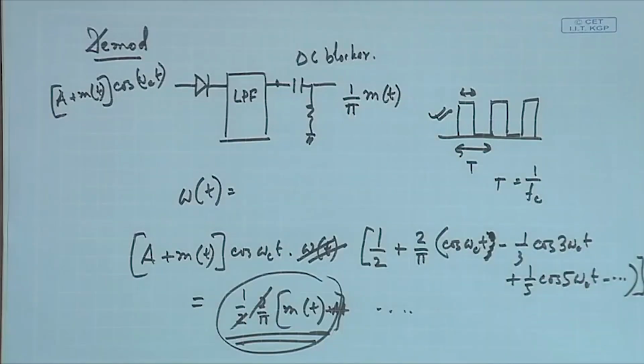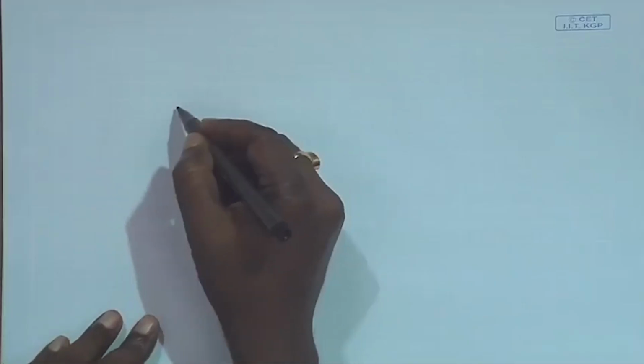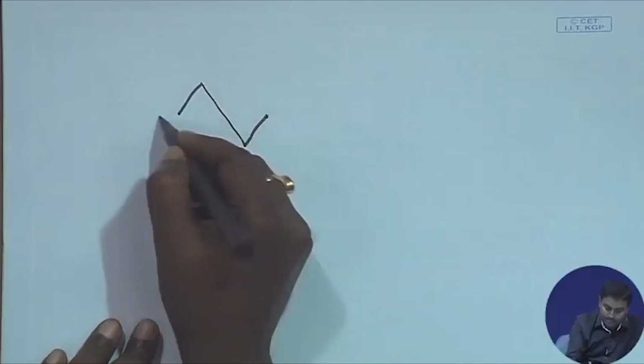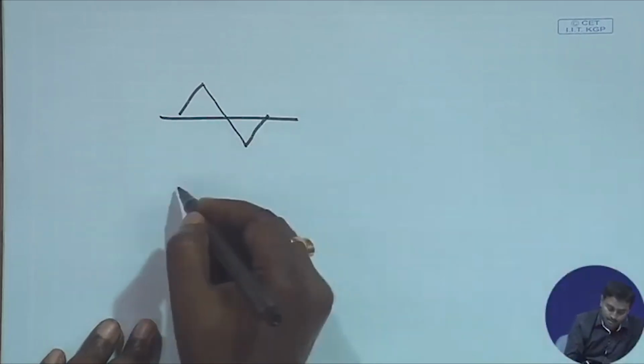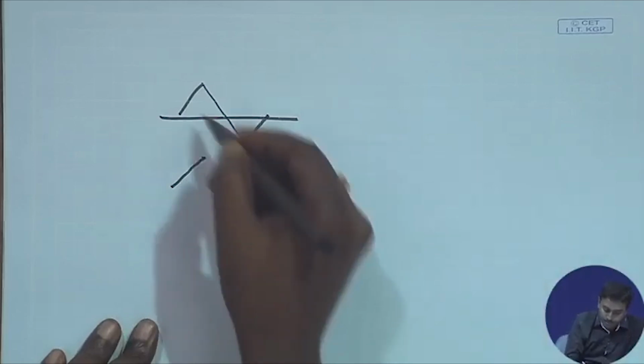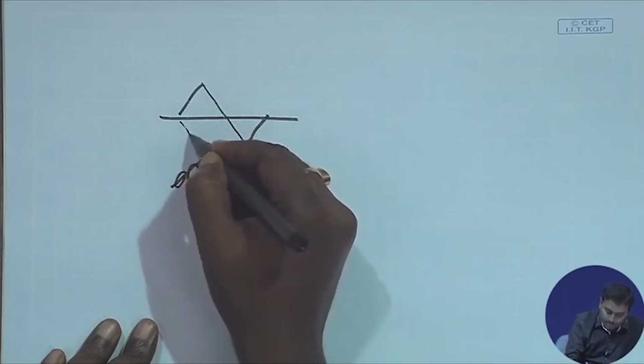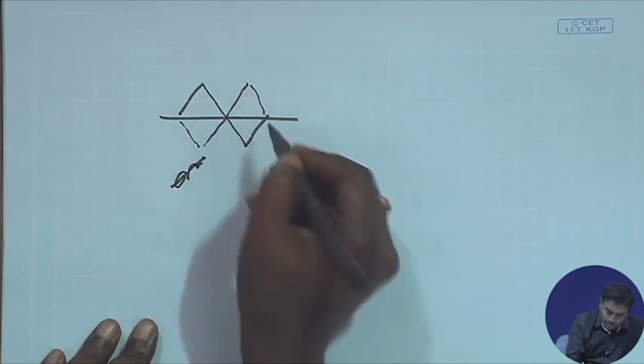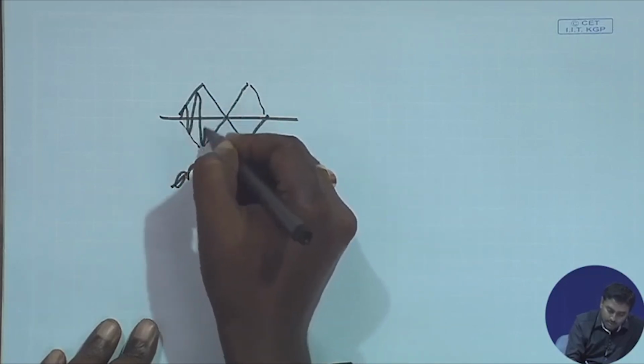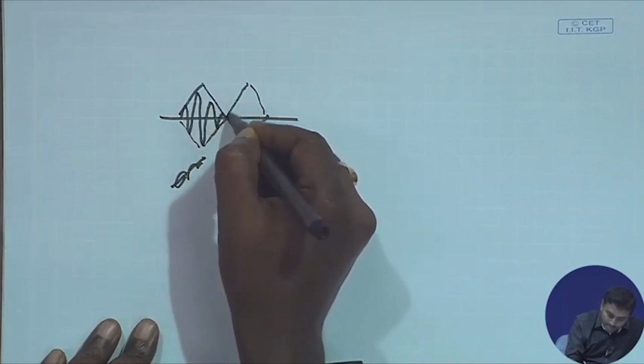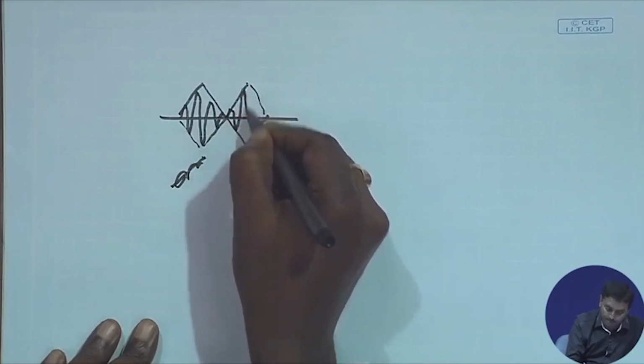You know why this is happening? Because this is a periodic signal, Wt I can write as a periodic signal. If there was a random phase reversal which was happening in DSB-SC, then what will happen? Let us see, I have a random phase reversal. So, my signal was like this, I do not add any DC. So, what will happen? This will become my envelope, and within this there will be a cosinusoidal which will have a carrier flip over here.